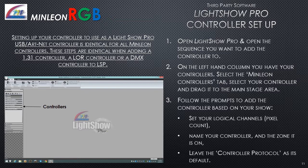On the left-hand column, you have your controllers. Select the Minleon Controllers tab, select your controller, and drag it to the main stage area. Follow the prompts to add the controller based on your show. Set your logical channels, name your controller, and the zone it is on. Leave the controller protocol as its default.